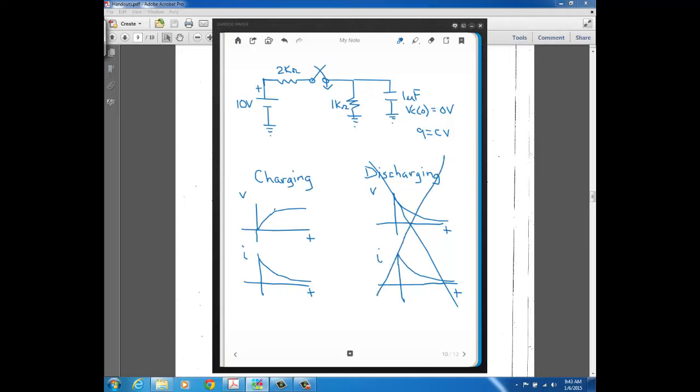Okay, so we're not going to have 2 decaying exponentials. What we're going to have is the voltage building up over time like this, going, a constant times 1 minus a decaying exponential, and the capacitor current's going to be decaying exponentially. So we need to find the voltage and current start points here, the voltage and current end points, and then also how long in between.